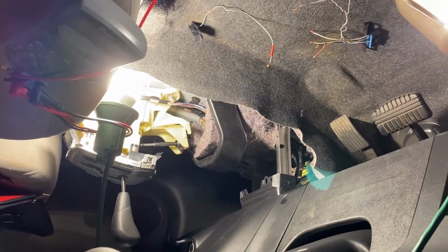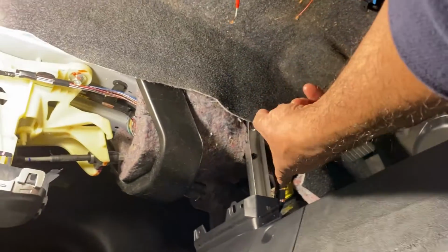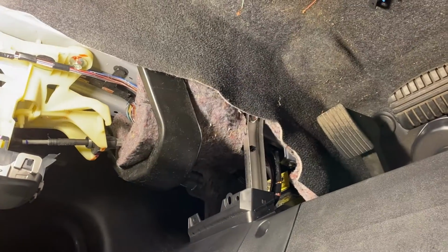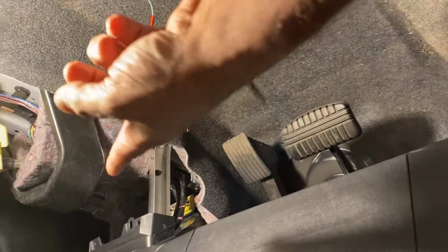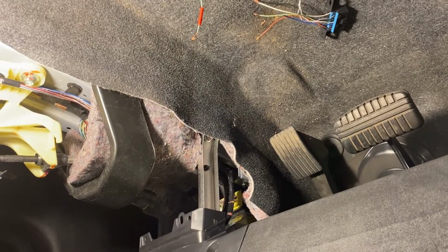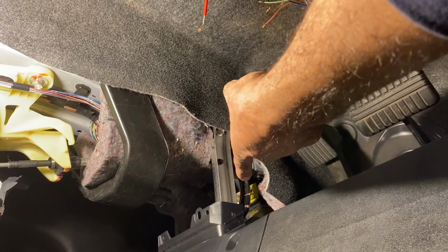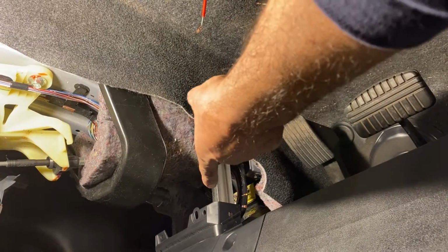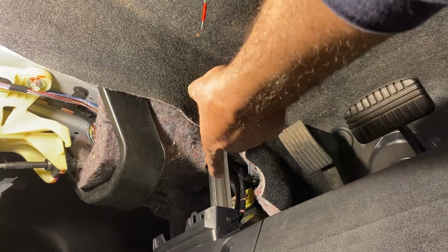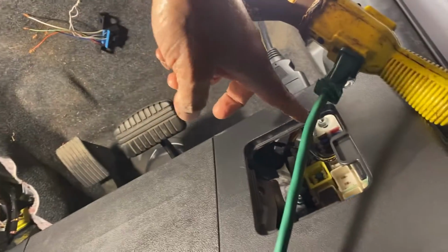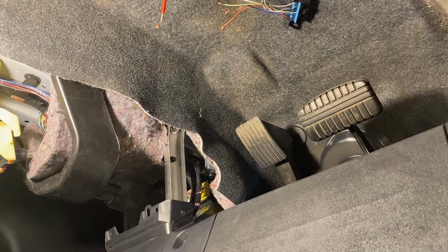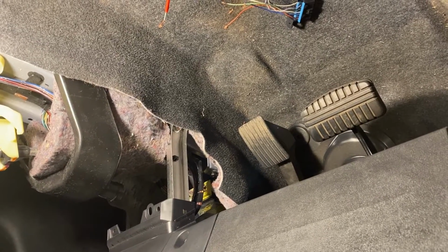But one thing you need to do is run a voltage drop between the power for the airbag all the way to the main power, or the power to the OBD, to see what's going on, to make sure you have a good connection. So you're going to do a voltage drop to make sure that you have volts, and then you're going to do a ground measurement between here and the battery, or between here and over here, to make sure that you have a good ground to the airbag. So hopefully that's it.